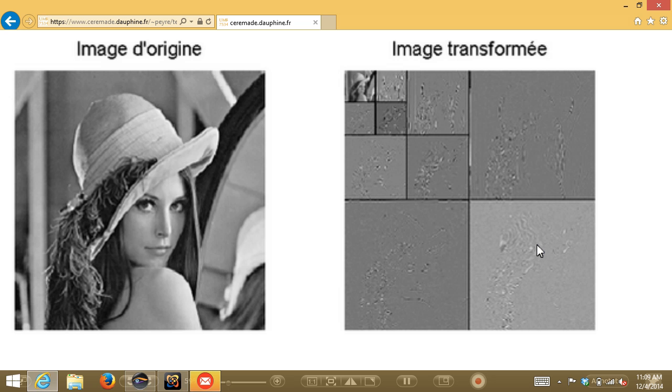Or maybe instead of getting rid of them entirely, I quantize them so that instead of having 256 gray levels in the edgiest image, I only allow myself 4 levels, right? Then I'm saving 6 bits on 1/4 of the coefficients, and that gets me some compression gain. Something like that. Does that make sense? Yes. So we need this kind of cascading. Yes, that's right. It's like a cascading version of the image. That's right.